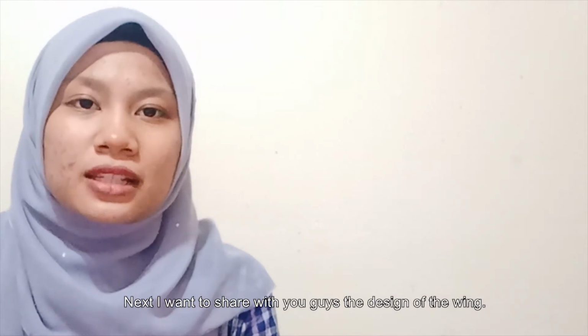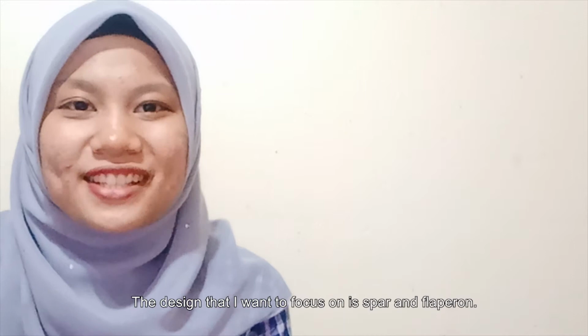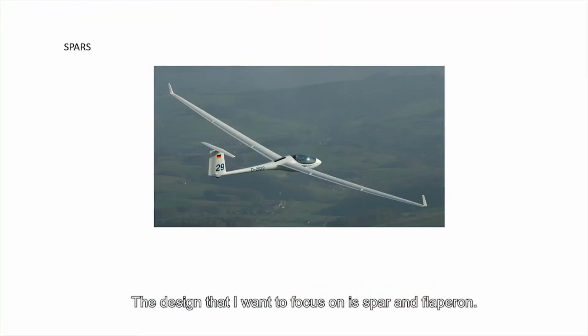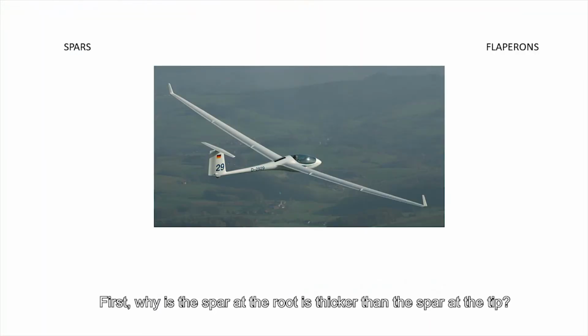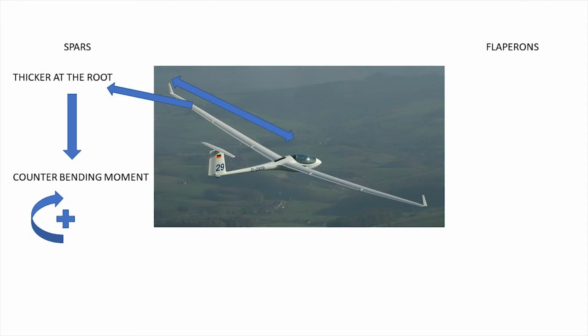Next, I want to share with you about the design of the wing. The design that I want to focus on is the spar and flaperon. First off, why is the spar at the root thicker than the spar at the tip? This is to give greater strength to support the larger bending moments.